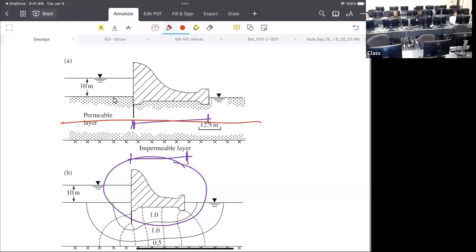First squeeze the dam, then we have to adjust the flow line at the intersection of the layers. But remember, when you're squeezing the dam and you have two different layers, you have two different units. Can we do two squeezings, a first transformation for the first layer, then considering the second layer, we transform again? Maybe you can take the smallest one of the scales and then squeeze it with the other things.